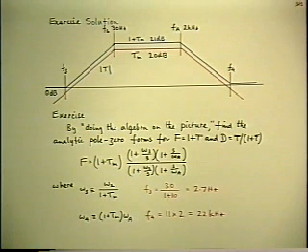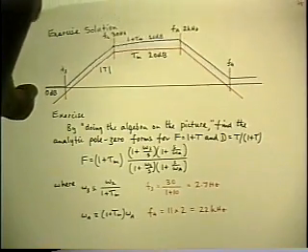I kept emphasizing in anticipation of this particular problem that getting this result by the graphical construction is much easier than doing it algebraically when the T gets to be more complicated. Well, it's a little more complicated this time in the sense that T has two poles instead of the single one that we started with originally. So just to emphasize how much worse the algebra gets already for this case, let's see what would happen if you tried to find F algebraically.